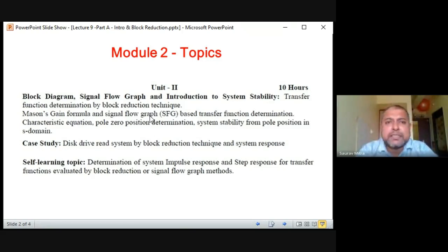Same thing if we are giving the input as delta(t) instead of a unit step, the Laplace transform of which is delta(s). So if we want to find out the system response with an impulse given as the input, we can find Y(s) equal to delta(s) times the transfer function ratio polynomial. From there, if we take the inverse Laplace, we can find out what y(t) is equal to.